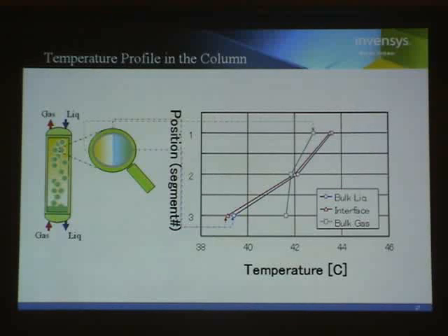You can also calculate the temperature profile in RateFrac. Because RateFrac assumes different temperatures for bulk liquid, interface, and bulk gas phase, we can consider the temperature difference between these phases, especially when vaporization occurs at the same time with absorption occurring.